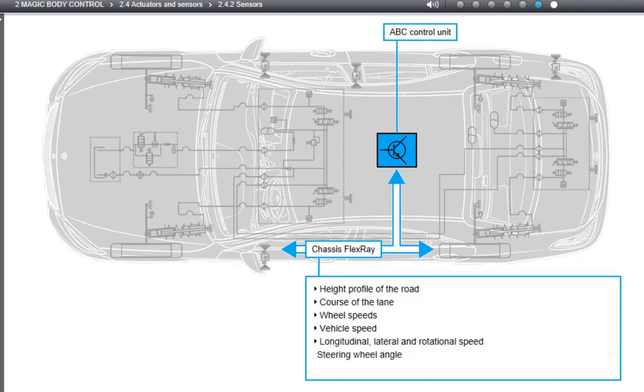The steering column tube module control unit sends the measurement values from the steering wheel angle sensor, namely the steering wheel angle and the steering wheel velocity. These supplemental data optimize the control of the suspension and damping system and support additional functions such as the crosswind assist to be discussed in the following.